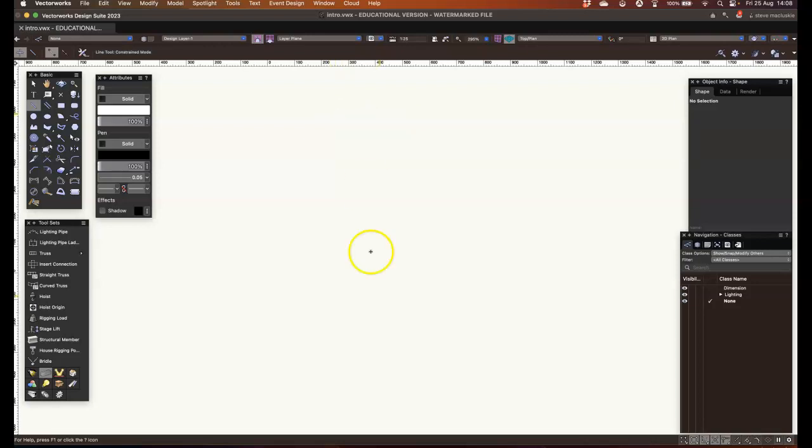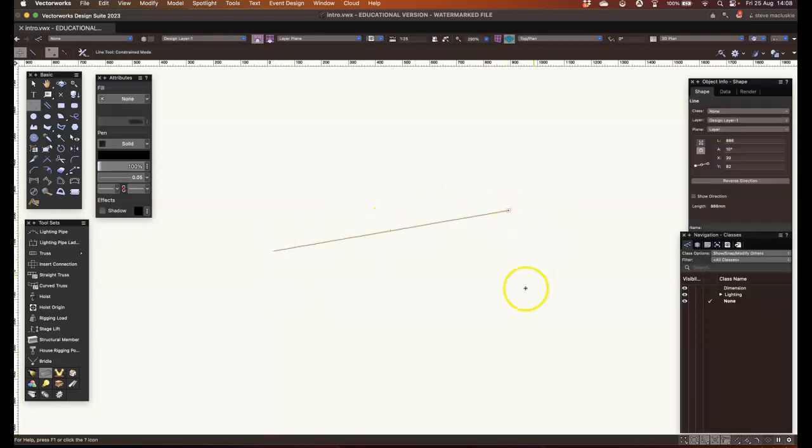So worth noting that we can edit the constrained angles. So if you were drawing a rake, meaning a sloping stage, 10 degrees would be very, very steep, but if you were making a rake, then by setting that angle there, it would be nice and simple to draw your 10 degree shape. There and there, that's it. I didn't have to draw a line and then pivot it, rotate it round. I just did it using the smart cursor settings.